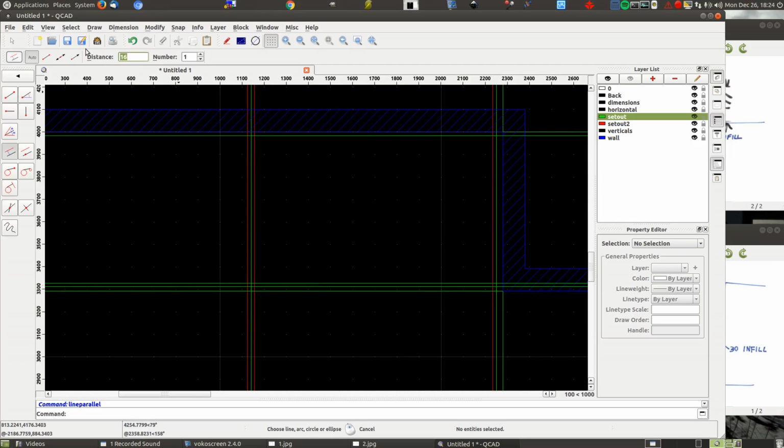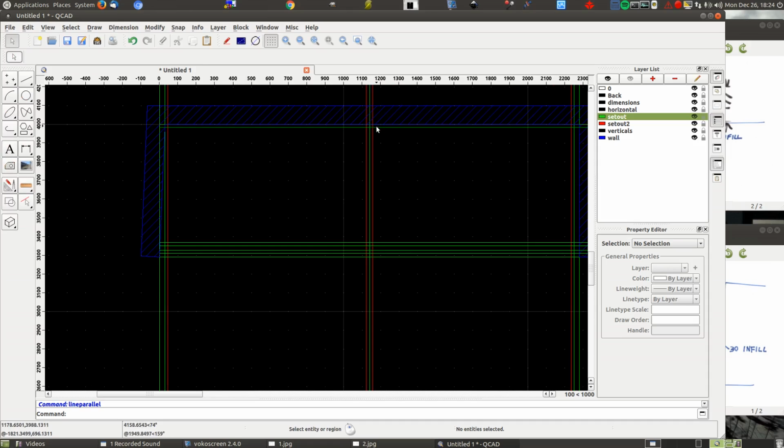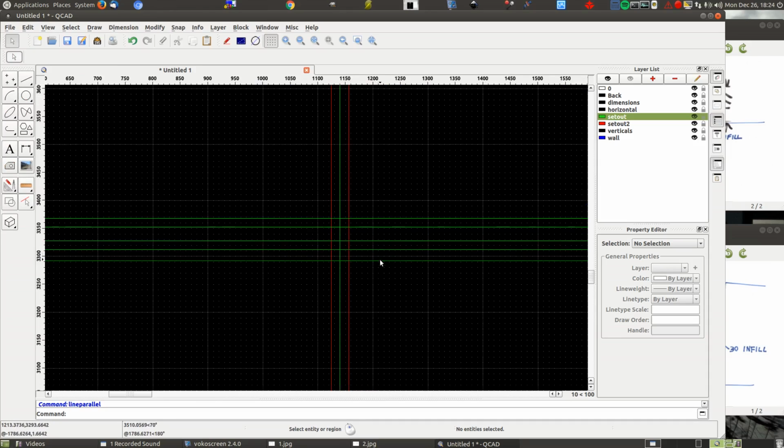Okay, 40mm is how far I want the kick to sit back from the front of the door. And I'm going to cheat simply by using the back edge of the door as my guide for the back edge of the kick, because they're both 16mm thick. If I needed some other measurement, I could have typed that in. Alright, so that's showing me the distances front to back. Right click to clear all that. Yeah, so I've got the thickness of the back. This distance here is the setback from the front. The thickness of the doors, the distance that the kick is set back from that edge, and so forth.